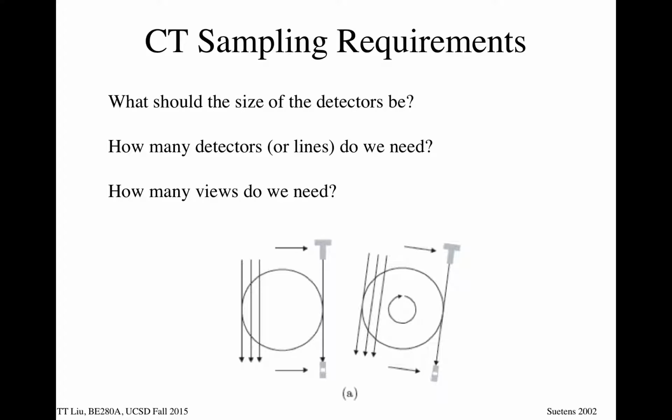So the question came up a couple of times. It's a natural thing to ask: what is the requirement for sampling? Since we've discussed the adequacy of sampling at a specific rate to avoid aliasing, in a CT scanner, what rate do you need to sample, both along a projection and in how many angles, to make a picture that has adequate resolution and a lack of aliasing artifact?